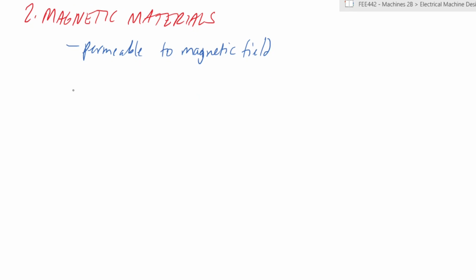They are most commonly ferromagnetic materials. They are almost exclusively alloys of iron. So you can add nickel, copper, cobalt, all those kinds of things into materials to create alloys that have various characteristics, whether it is high permeability or low permeability, depending on the applications that they need to be used for.